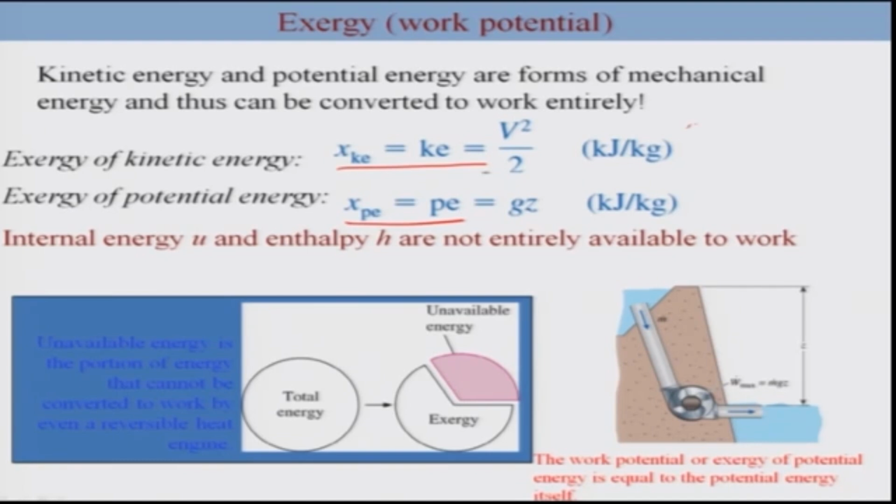However, this is not true if we consider internal energy and enthalpy, which are macroscopic, molecular level microscopic energies, and they are not entirely available to work. On the other hand, mechanical energy such as kinetic energy and potential energy are entirely available to work, and thus exergy is directly related to the corresponding energies. This is the schematic representation of total energy, and the only part which is available would be your exergy, the rest would be unavailable energy.